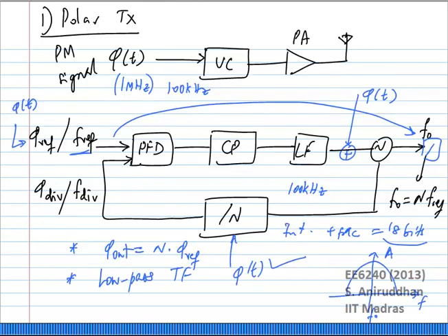and so we said that if the waveform is primarily phase modulated, then you can ignore any distortion in the amplitude generated by the up converter, because really you are interested purely in the phase of the output signal from the transmitter. And obviously if you look at it in the IQ domain, you will have both I and Q channels.